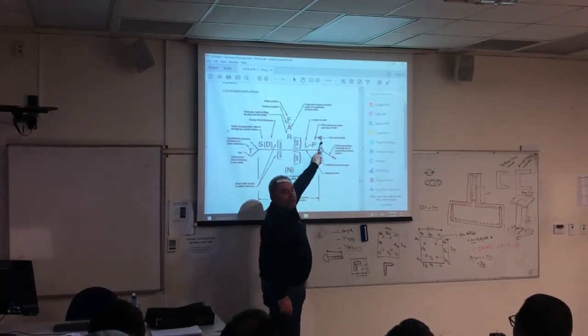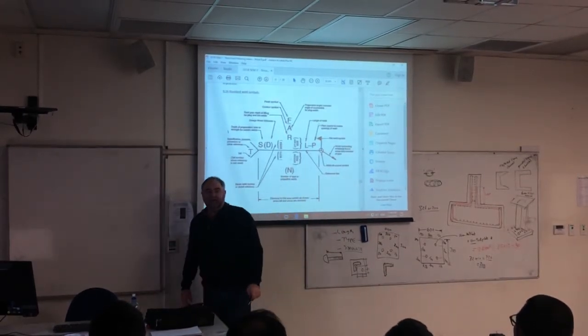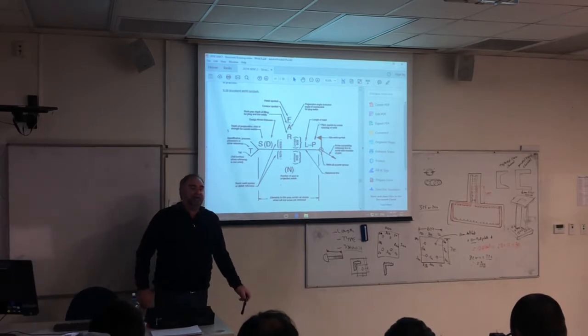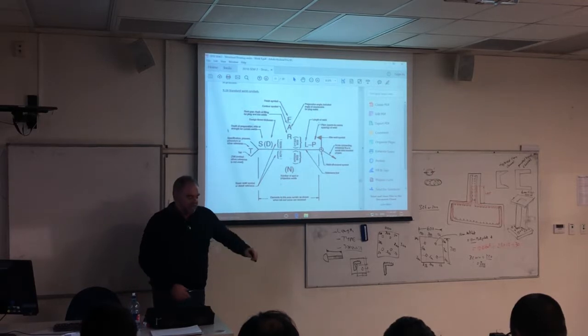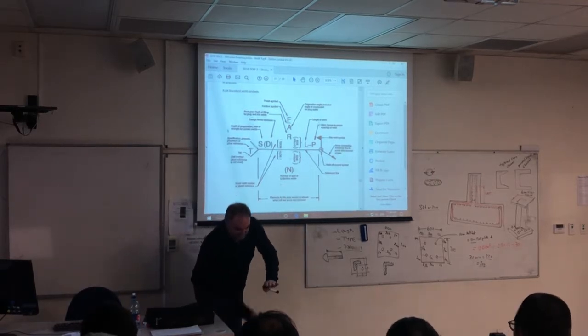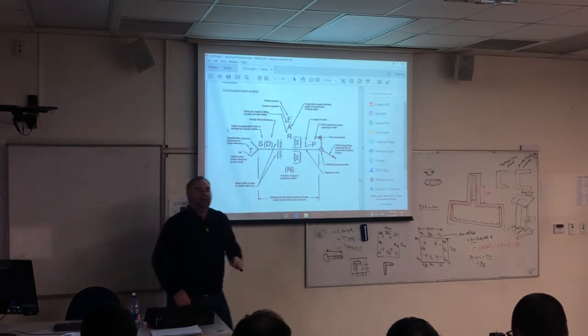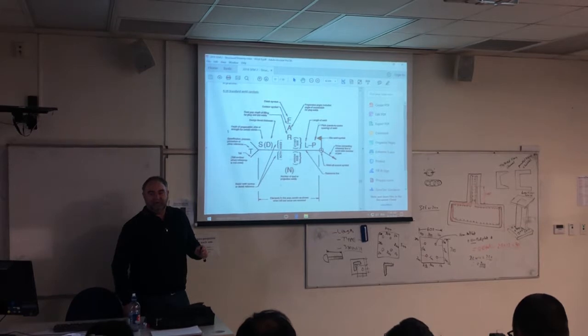This little golf flag means on site. I've already told you today, if you review the tapes, I've already told you whether it is an on-site weld or not. It's about this high. The angle goes down between two plates. Would you weld that back in the factory and deliver it to site, or would you do the welding on site?